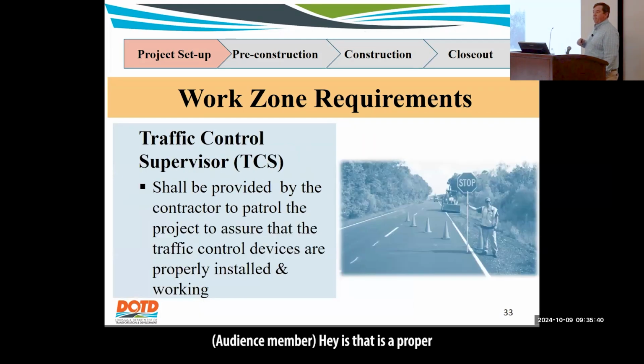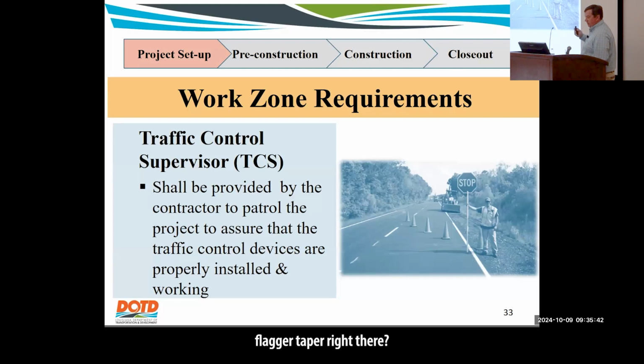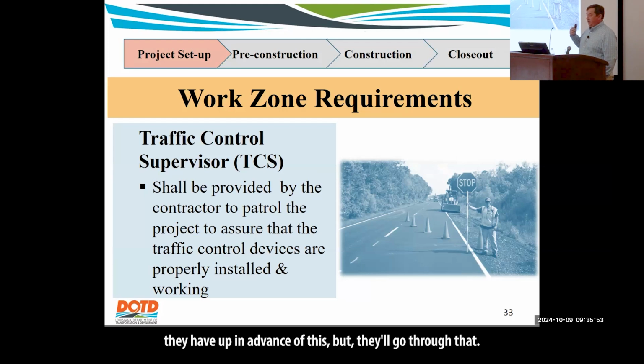Is that a proper flagger station right there? It actually, yes, it does look proper. Now, I don't know what sort of signs they have up in advance of this, but they'll go through that, I know, in a little bit. But he's standing there with the sign out. He's not in the middle of the roadway where he's going to get run over. The cones are tapered to force them over, that sort of thing.